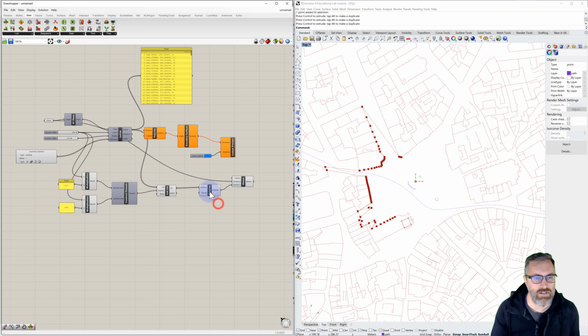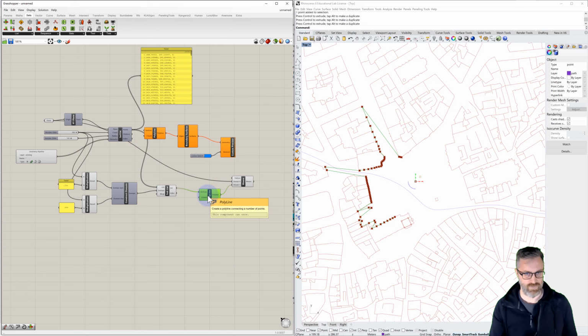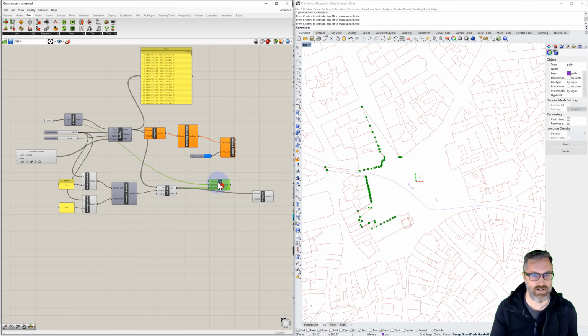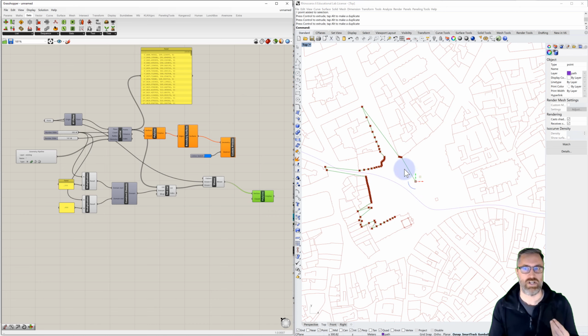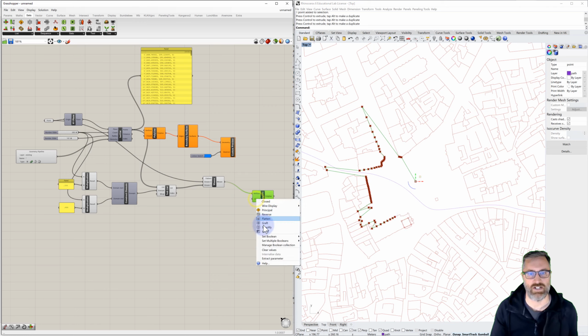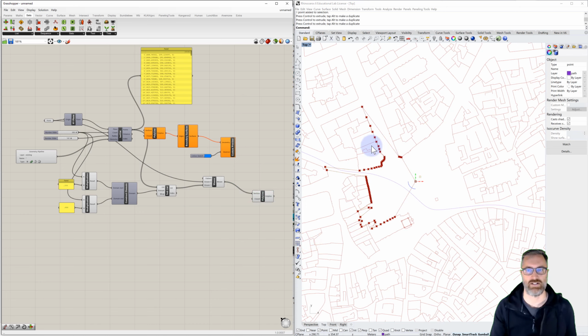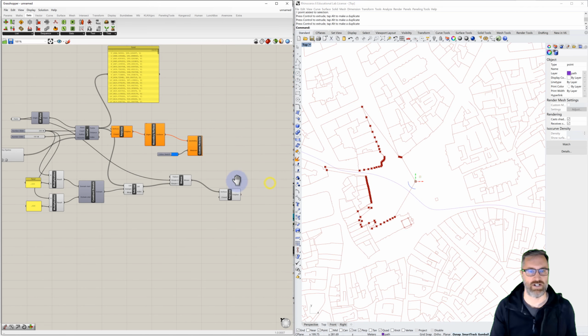And now, I actually want to move the polyline to the other side. Let's plug our list in here. And we'll do that. And so now we can see that with our weave, we just created a polyline from our first point, from our point out to our polyline and around. And now the trick is that we can just set closed to be true. And now this is a closed polyline all the way around, originating from our point.